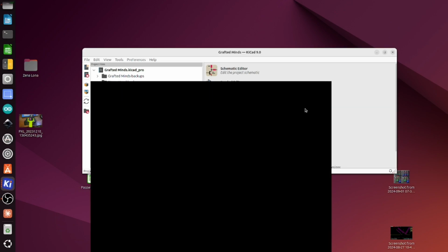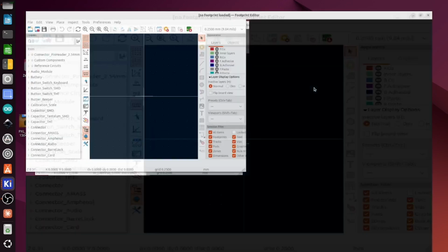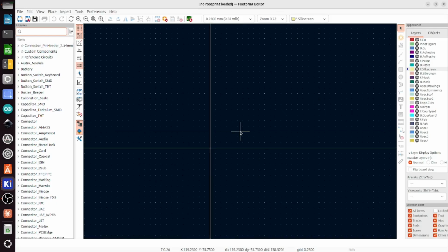I'll go into the footprint editor. It's worth a whole other video another time, but what I've found is that I get all my parts from lcsc.com. Even after tariffs, they are just cheaper by a landslide, and it's faster, to be honest, than the domestic parts houses. So they have a really nice symbol library. You don't have to beat around the bush too much to find a symbol for any part that they have. So what I do is I open those in Easy EDA, export them as a JSON, and then import them into here. And I don't draw any symbols really, very rarely.